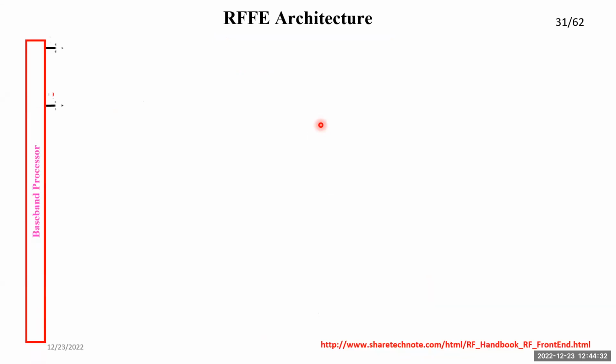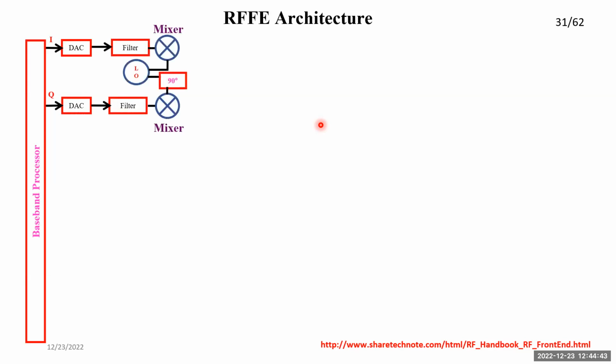Next, as we are from the RF background, the RF front end will have, for example, IQ samples coming out of the DAC. Then you will have filters to suppress the out-of-band noise. Then you will have mixers to convert that into another frequency. There are two kinds of conversion: one is digital-based up conversion and down conversion. Similarly, for analog also, you have up conversion and down conversion.